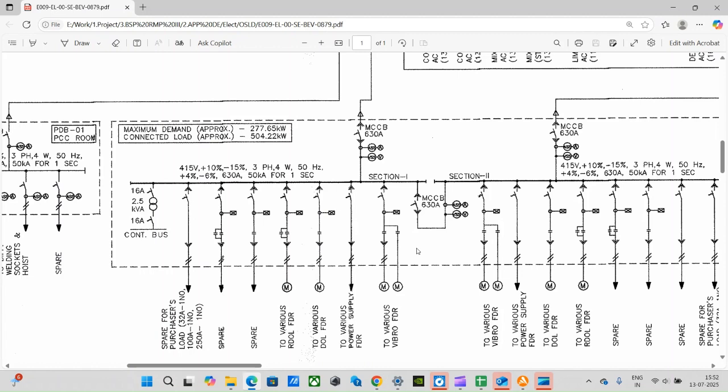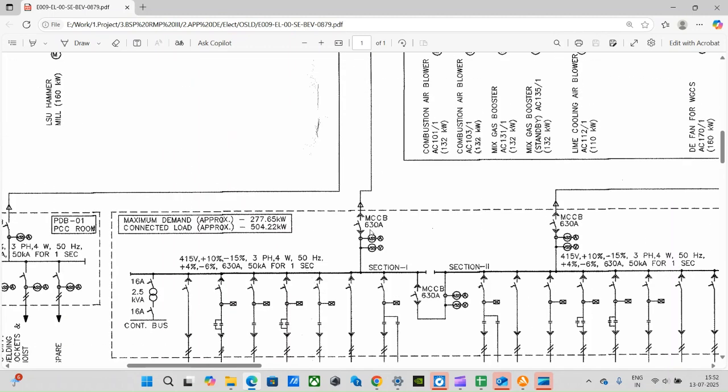Always remember this. If you are going to work as a design engineer, this configuration won't work. This intelligent controller will not capture any of the faults correctly, because the two motors are combined, and overloading also won't be able to be set. So the bottom line is this configuration is not correct. You need to take two separate intelligent controllers here. I think that is what I wanted to tell.